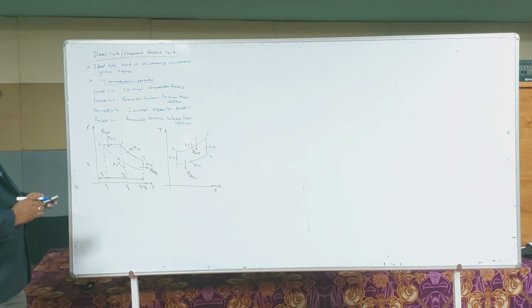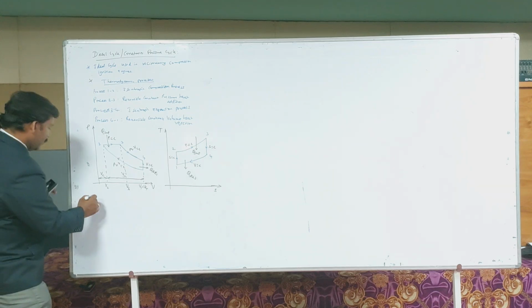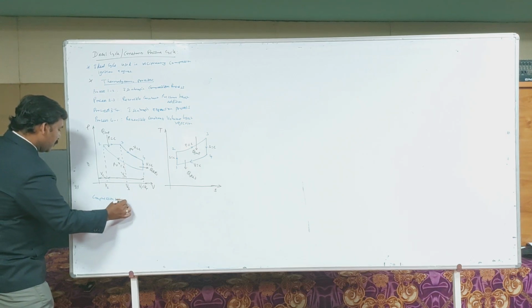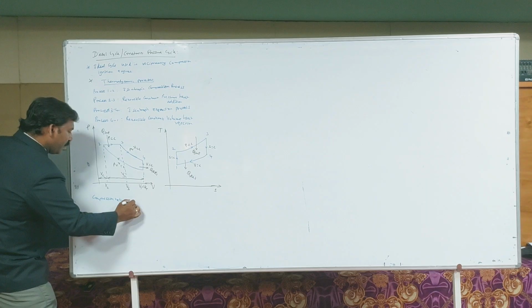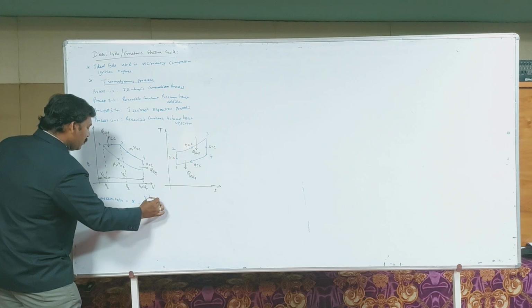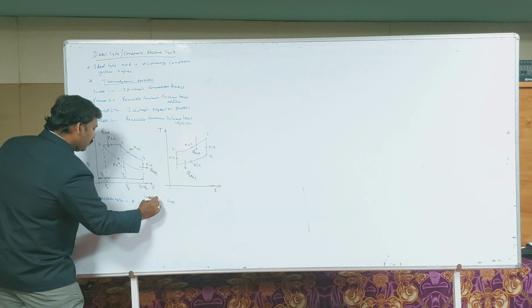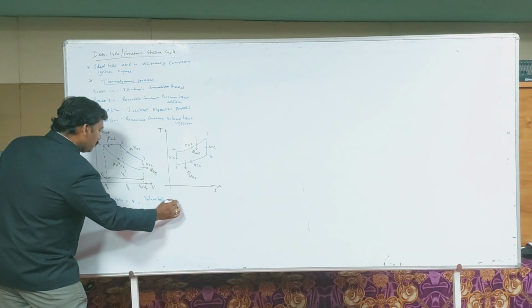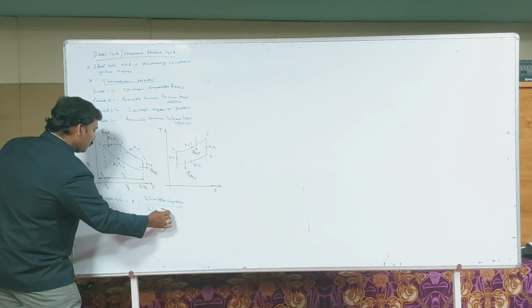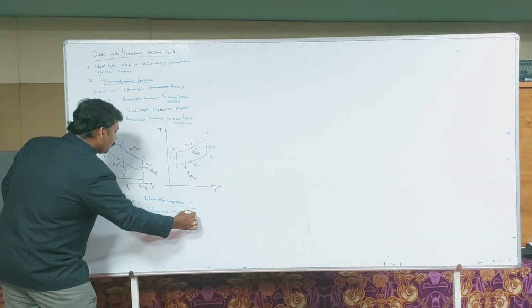Now in this PV diagram, there are certain ratios to be remembered. Let us start with the first one, the compression ratio, which is denoted using the letter r. Compression ratio is defined as the volume before compression to the volume after compression. So that is equal to V1 by V2.